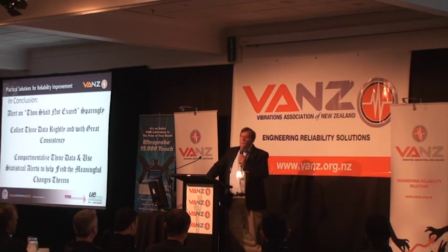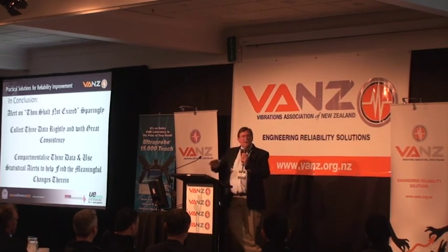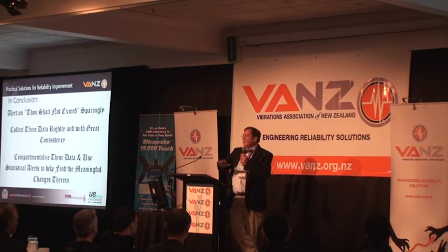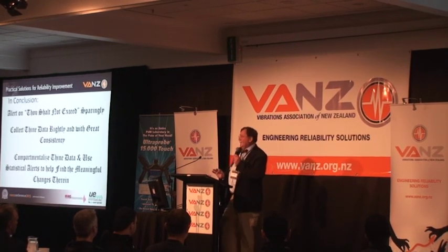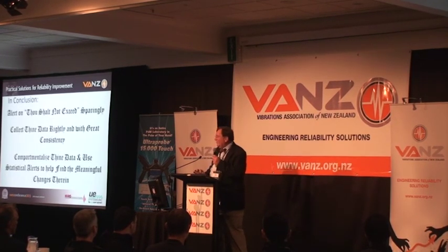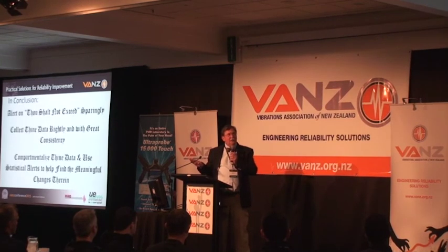If you looked at a run up and a coast down on this machine, the quietest, the calmest part in the spectrum was when you were running through 1500 RPM. And at 1800 RPM, for supplying 60 hertz power, you were actually on the upslope side of the second critical.